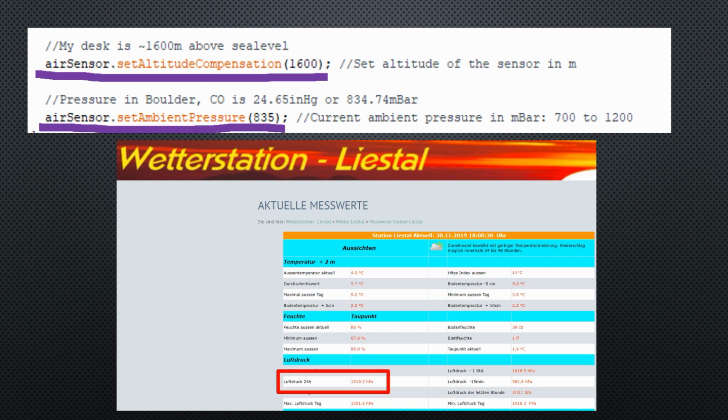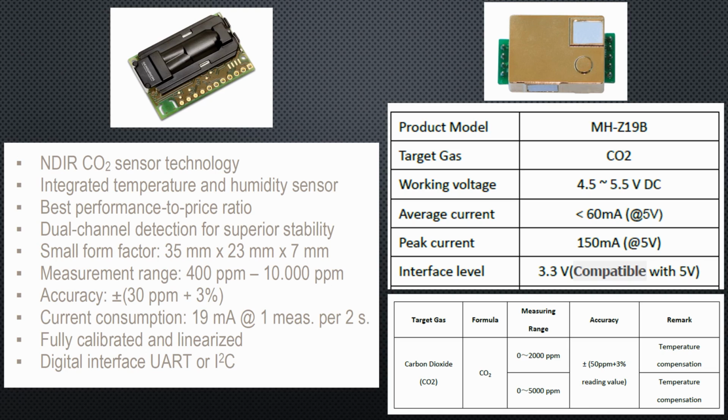Another fact you have to pay attention to. After startup, the values are imprecise. Only after 30 minutes or so they are okay. This is not a big problem for indoor air monitoring, but it can be a problem if you want to do measurements for experiments where values change quickly. CO2 sensors are no low-power devices.